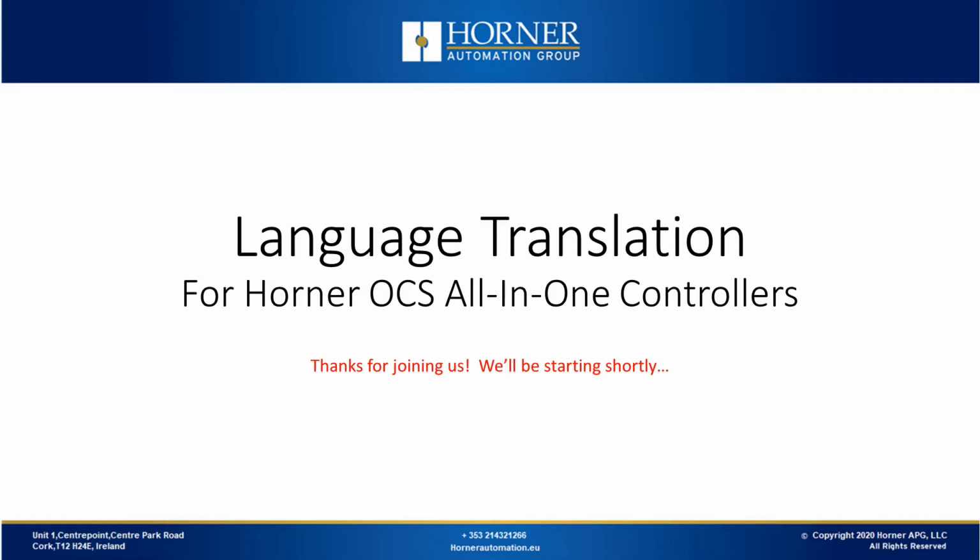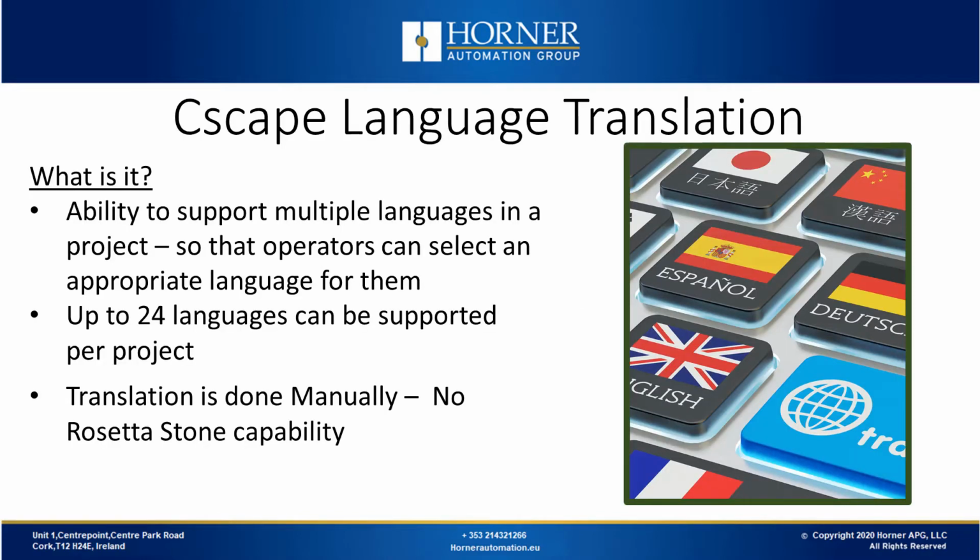Welcome to today's tutorial. Today we will be discussing Cscape language translation and font handling. Let's talk about Cscape language translation. It's the ability to support multiple languages in a single project so that operators at runtime can select an appropriate language for them. You can support up to 24 languages in a single project. However, translation is done manually.